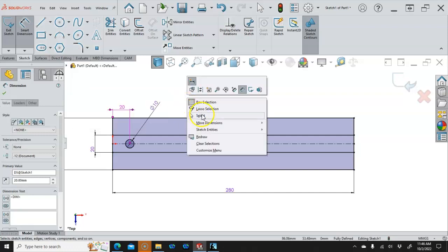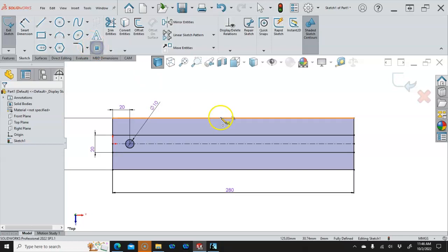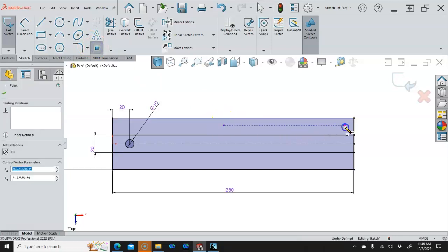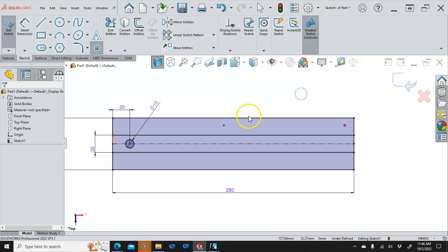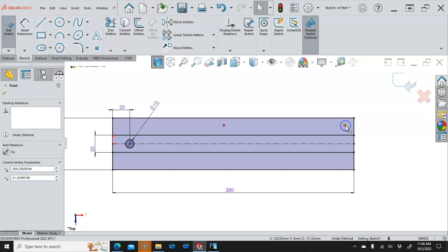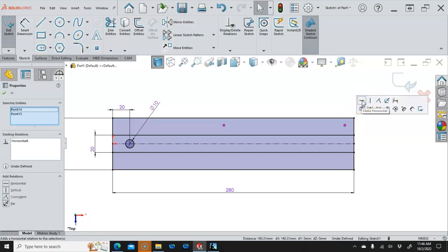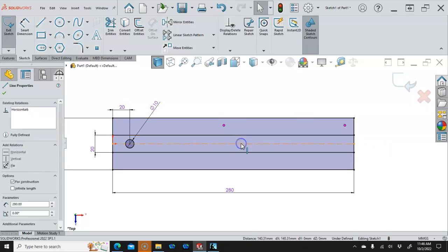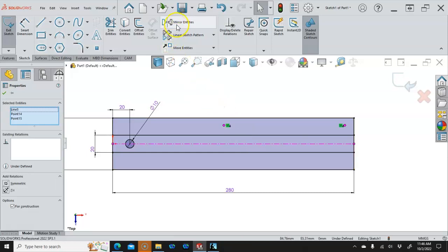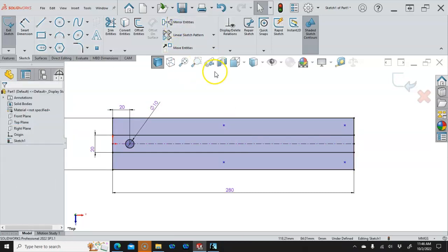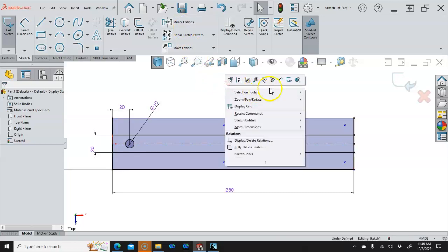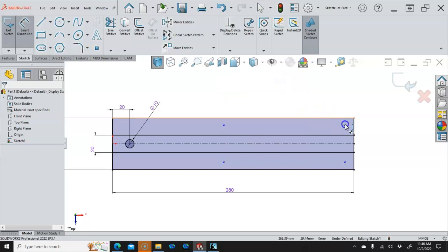Okay, and then for the hole locations, we'll introduce the hole wizard. So I'm going to draw 2 points for the 5mm hole locations. Make those horizontal. Since they are still selected, I can tell they're selected because they're in the magenta. Again, yours might be blue or grayish, depending on what you set. Control select the center line, go to mirror, and now we have those geometries established.